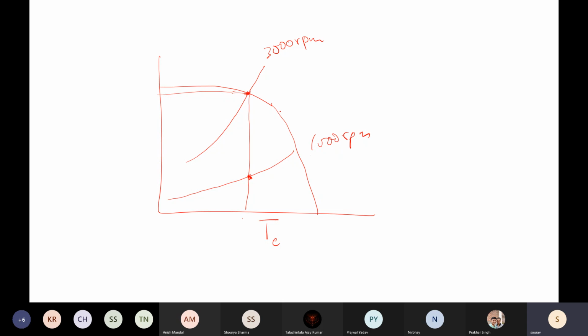The evaporator gets flooded, the pressure inside will rise. Okay, once the pressure inside rises, instead of operating here, you will be operating here. At this condition, you will have this much flow rate provided by your capillary tube. And this will continue to go on till you reach a new balanced condition, which is this.